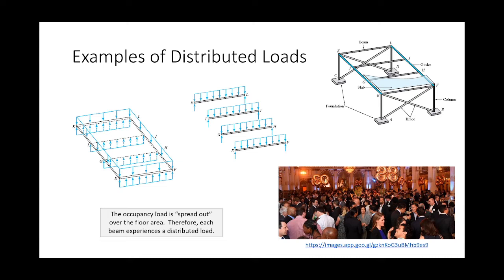Let me give you another example that'll hit a little closer to home. When you are designing a building like this one, the Weisberg Applied Engineering Complex, the structural engineer will design the classrooms for a live load usually of around 40 to 50 pounds per square foot. That live load is meant to simulate you and me, the desks, the computer, what the room is used for.